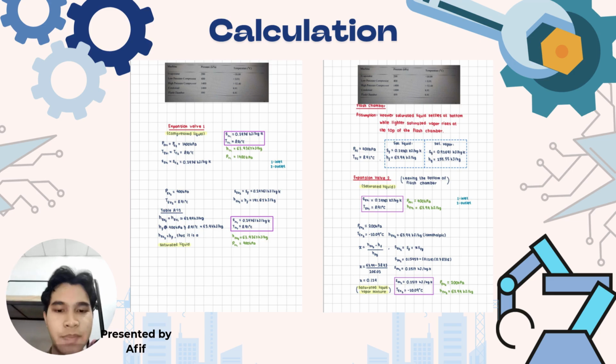So now we're moving on to the first expansion valve after the condenser and subcooler. It's going to be compressed liquid at the inlet, and the outlet is going to be represented by saturated liquid. And it is an isenthalpic process, meaning the enthalpy doesn't change throughout the valve. And then we move on to the flash chamber. The flash chamber is going to separate both the saturated vapor and liquid at the same time. And since the second expansion valve is connected to the bottom of the flash chamber, the inlet at the expansion valve is going to be saturated liquid. And after it exits, it becomes a saturated liquid-vapor mixture.